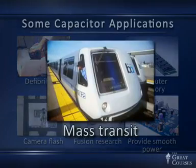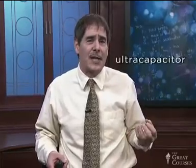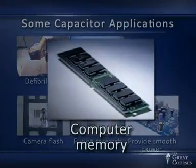In the middle frame at the top, you see a mass transit train of the Bay Area Rapid Transit System in the San Francisco Bay Area. As BART trains come into the station, they don't put on frictional brakes to dissipate their energy. Instead, the energy runs an electric generator, which stores energy briefly in a capacitor, a so-called ultracapacitor, and as the train accelerates out of the station, it uses that energy, so the total energy consumption of the train becomes much less. On the top right, you see computer memory, which is another example of energy storage in capacitors.